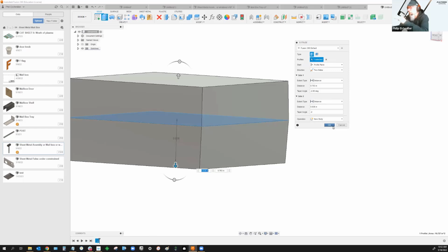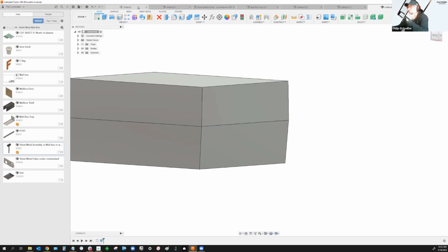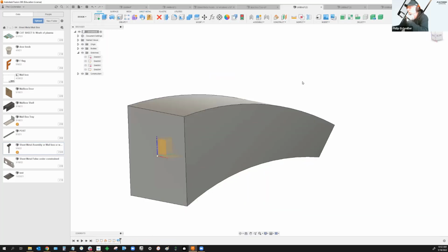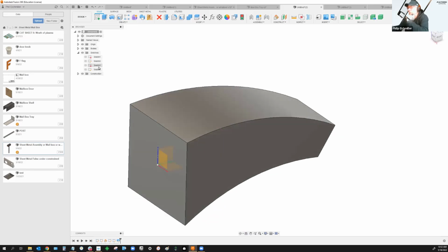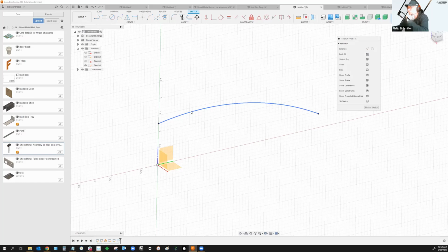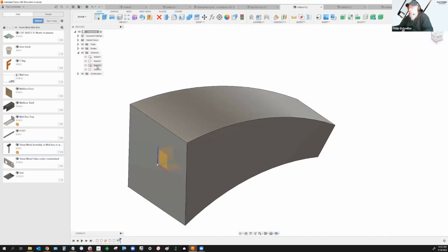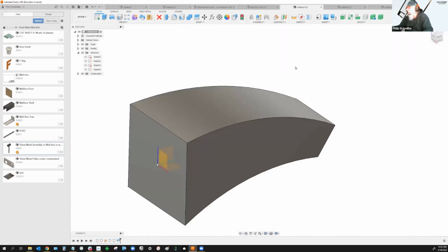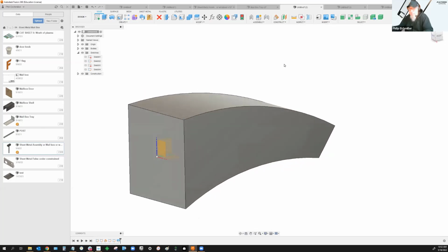So if you know where that parting line is and you can define it, where's the loft? Did I retain that or did I blow it out of the water? Oh, here it is. So thinking about it this way, if this sketch represented where that rail is, represented the parting line of this lofted part, then yeah, absolutely, it works great. What I would wind up doing is changing these things to build in that draft right here on these profiles. So your sketch profiles get more complex, but you can build that parting line right into your loft if you need to. Hopefully that helps.